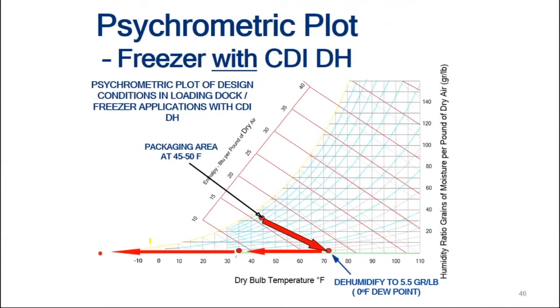How do we get that much moisture out of it? How much is practically possible? With the desiccant product, and we're just showing a condition here starting in a kind of a cooler, wet condition, which would be similar to what you're seeing on the loading dock. As that goes through the desiccant unit, rule of thumb, we're getting a 30 to 40 grain depression.